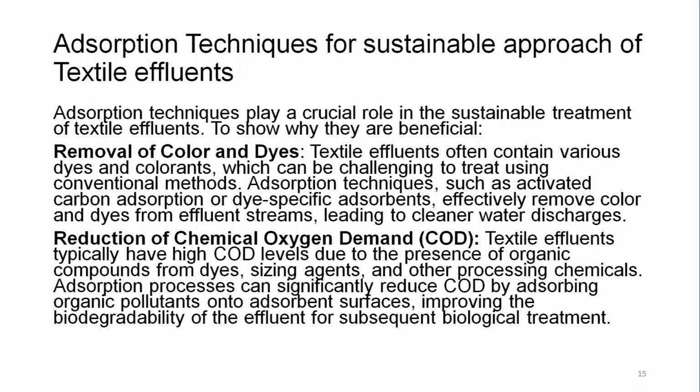Reduction of chemical oxygen demand, that is COD. Textile effluents typically have high COD levels due to the presence of organic compounds from dyes, sizing agents and other processing chemicals and auxiliaries. Adsorption processes can significantly reduce COD by adsorbing organic pollutants onto the adsorbent surface, improving the biodegradability of the effluent for subsequent biological treatment.